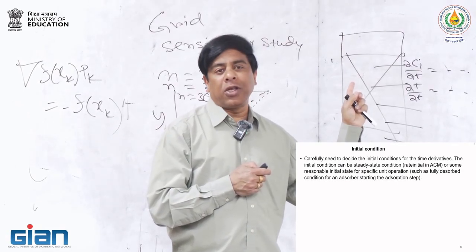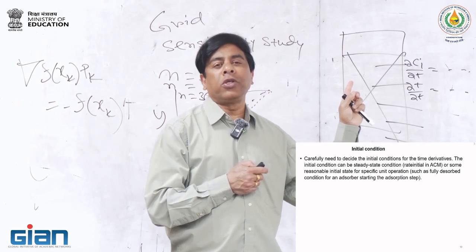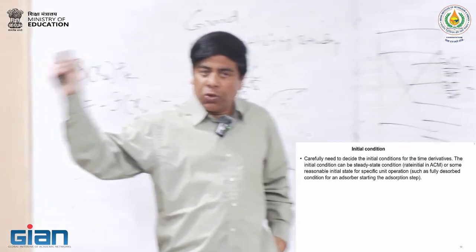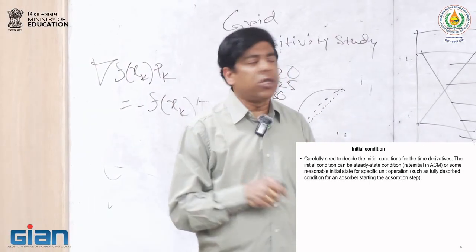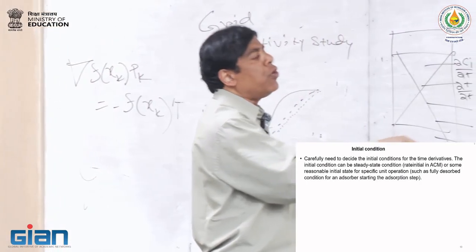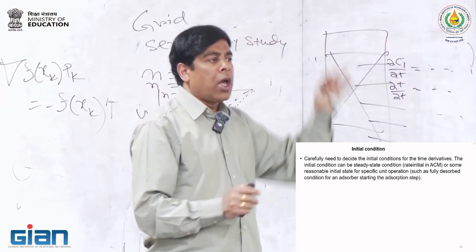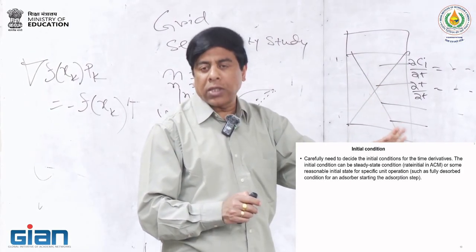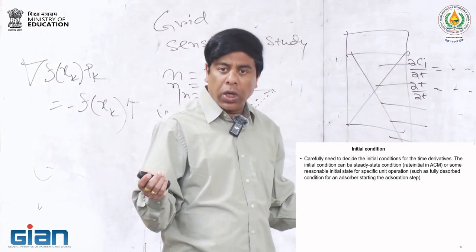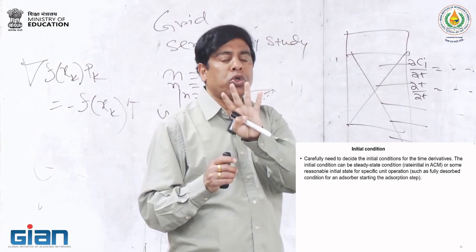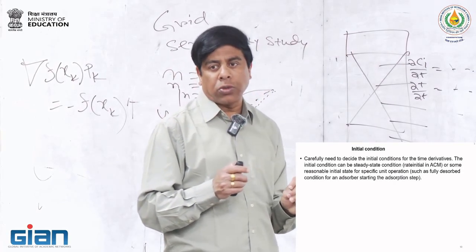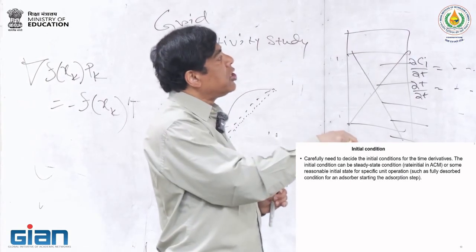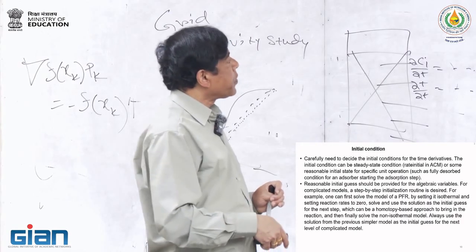This is really the trickiest thing for adsorption. We do not know what the initial state is. So you have to go for some simplicity, and that will be a future discussion. You can say, okay, I can consider the initial state to be when the bed is fully regenerated, so there is no loading, and the concentrations everywhere are at the inlet concentrations and so on. That's the best guess you can make, right? And that's okay. I will talk more tomorrow about adsorption systems. But if you are doing a PFR or a CSTR, which has a steady state, this rate initial is a wonderful option.